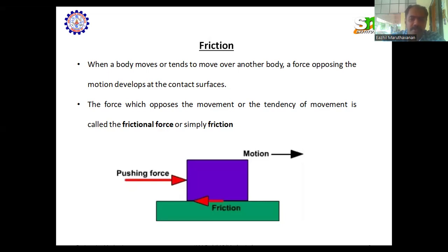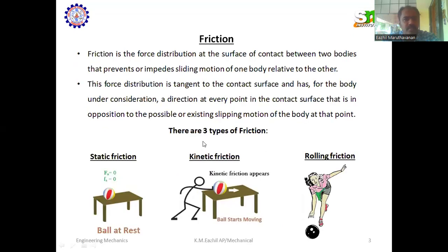First, the amount of friction is nearly independent of the area of contact. For example, if a brick is pulled along the table, the frictional force is the same whether the brick is lying flat or standing on an end. Second, friction is proportional to the load or weight that presses the surfaces together. It is a tangential force that occurs between the contact surfaces.